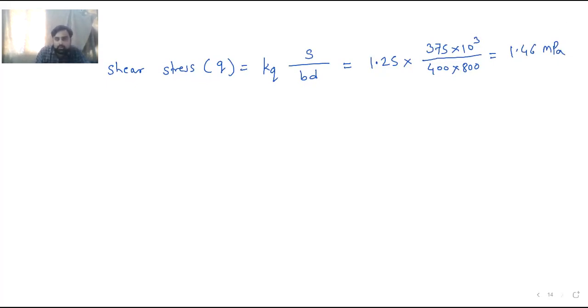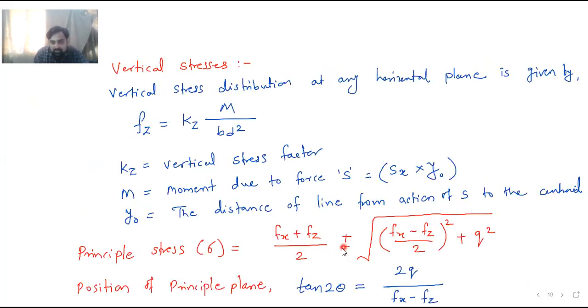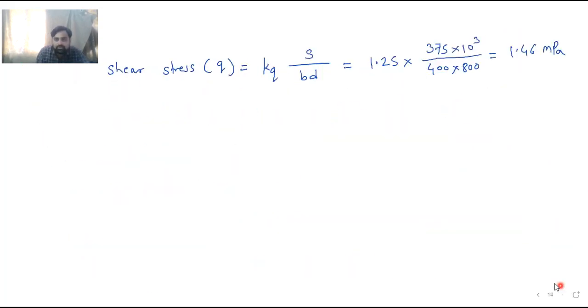Okay, so in the numerical, what they have asked us further is, find also the principal tensile stress at the above section. Principal tensile stress they have asked us, not the compressive stress. So principal tensile stress means minus sign we need to use. So next,